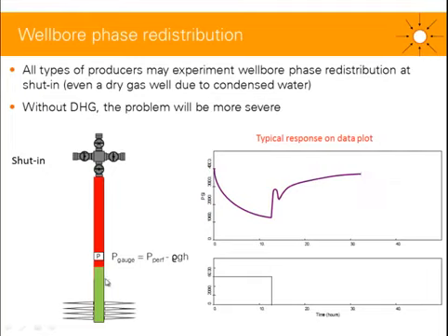But on some occasions, liquid might be reinjected in the reservoir due to, let's say, gravity or gas expansion in the tubing, and then the liquid-gas interface might go down the well like this. And now again, the density below the gauge is changing over time. The fluid below the gauge is getting lighter and lighter, this term smaller and smaller, the density. So now the pressure at the gauge will increase, not only due to the PBU, but due to this density getting smaller and smaller, or the fluid getting lighter and lighter below the gauge. It will have the same effect as a PBU, and it will be quite difficult to see.